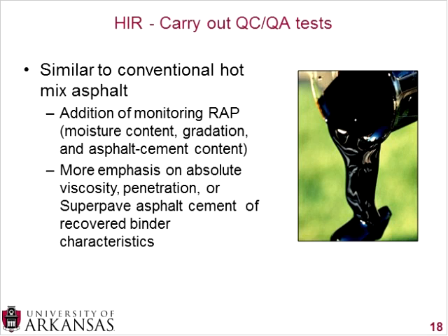And once you have completed the mix design and you have recommended what mix design to use in the field, once you get out there in the field, again, it's pretty similar to conventional hot mix asphalt or cold in place recycling, depending on kind of what angle you're going for. Because you're using in-place material, you do want to monitor what's going on with that RAP. If it had just rained, you may have some moisture problems. The heating does certainly evaporate a lot of that moisture, but it may not evaporate all of it. So you want to make sure you have a moisture content in line.